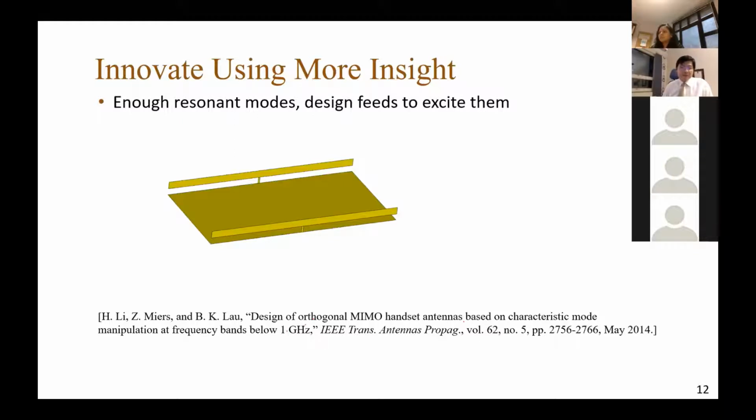But with respect to dielectric material on the smartphone itself, because the amount of material is not so much, I think it's generally okay to just consider the loading effects. They will likely slightly detune your antenna to a lower frequency. It's just a loading effect, and they do not by themselves effectively form new modes that you could use. I don't think so. Yes.